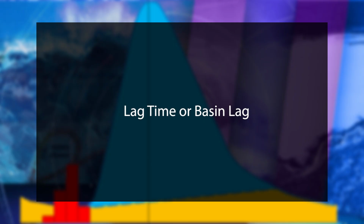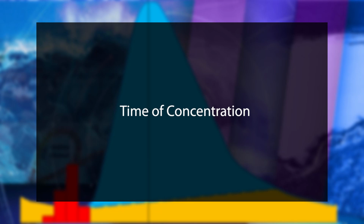Lag time or basin lag. Lag time is the time difference between the center of mass of effective rainfall and peak of the unit hydrograph. Time to peak. This is the time interval between the start of direct runoff and the occurrence of the peak discharge. Time of concentration. It is the time taken by runoff from the most distant point of the watershed to reach the outlet. It depends on basin length, slope and surface characteristics.